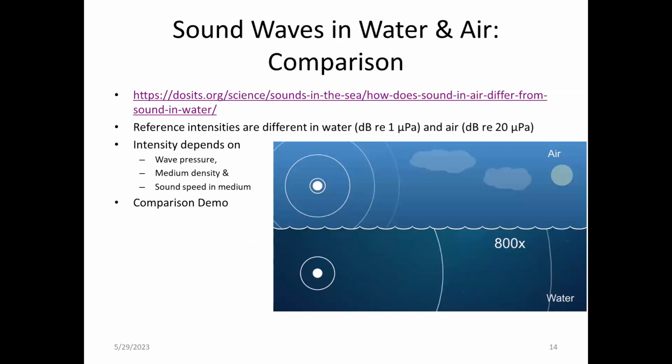We could have decided on some other convention, but by convention, in air we use 20 micropascal as the reference sound. The reason is that this is the power of the minimal sound that the ear can perceive. For example, the sound of a mosquito would be around 20 micropascal. For water, the reference is 1 micropascal, which is a more generic selection that has been taken as the reference for underwater applications.